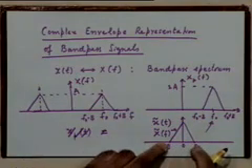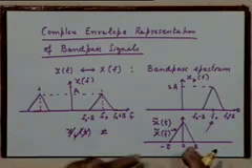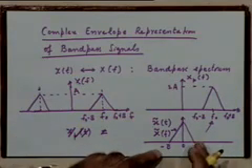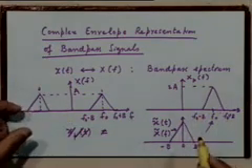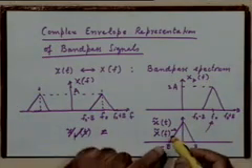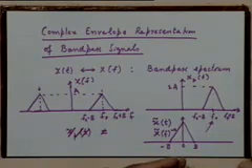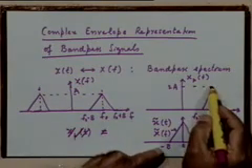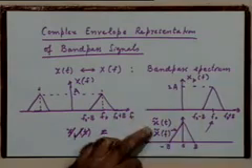This signal is a low pass signal because its spectrum centers around 0, and in general it would be a complex valued signal. In particular it could be real valued if the symmetry here exists, right? In general it would be a complex valued signal, and these two signals would be related by a frequency translation operation. That means xpt would be x tilde t multiplied with e to the power j2 pi f naught t, plus, because it's shifting to the right, right?